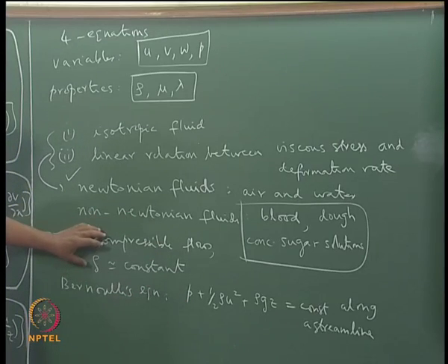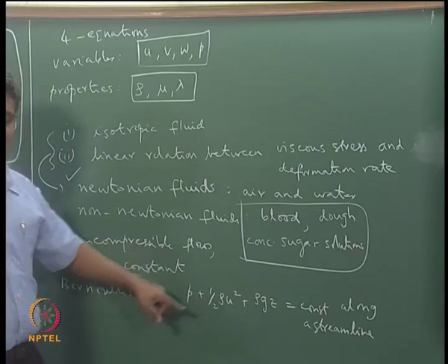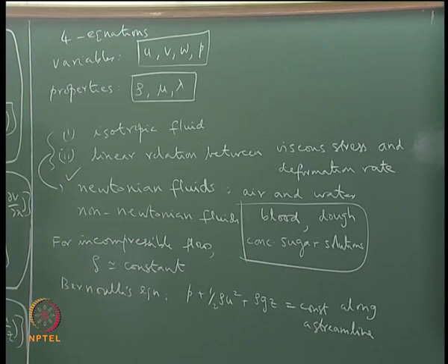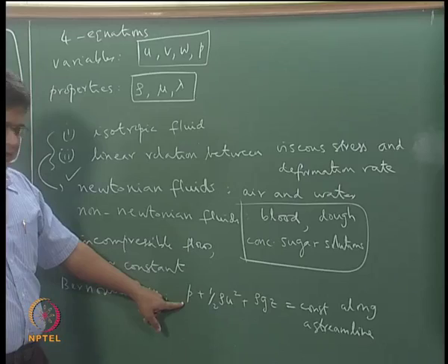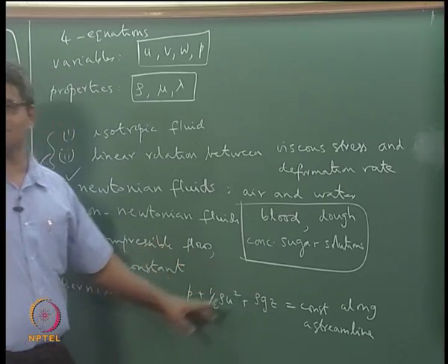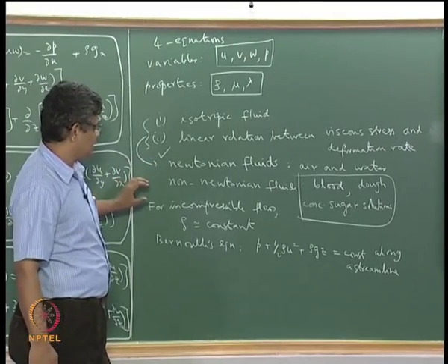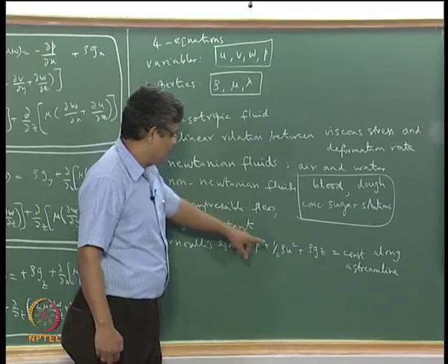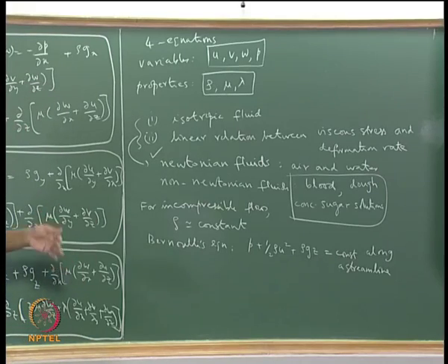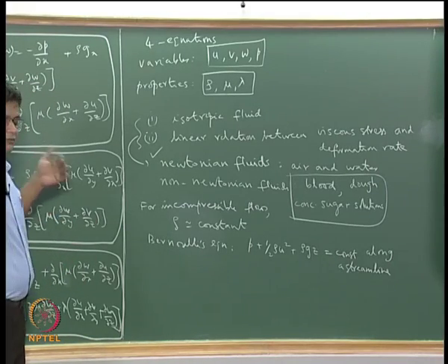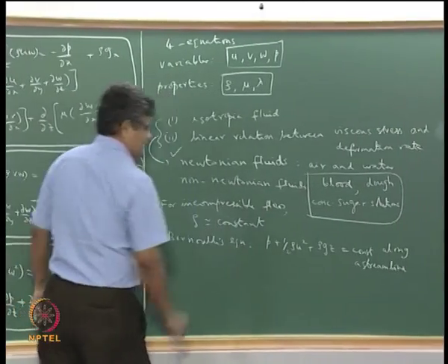When we say that the flow is incompressible, we are saying that the velocity changes arising out of all the forces that are acting on it as the fluid goes along a streamline do not cause sufficient changes in the pressure that the density is greatly affected. So that is the condition of incompressible flow that we are bringing here. So that is why incompressible flow is a flow property. It is related to the velocities and the pressure and then the corresponding density. It does not talk about the fluid itself. So you can have an incompressible flow even of a gas. So for such cases we can say that density is constant.